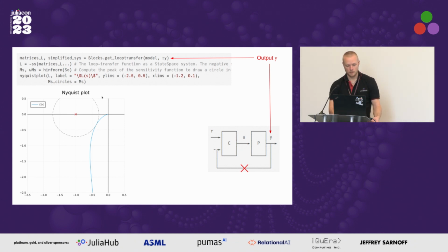And if you're familiar with Nyquist theory, you might recognize that we want to stay far away from this, called the critical point here. If this blue curve encircles this critical point, our feedback connection is unstable. So typically we would like to be far away from that point.